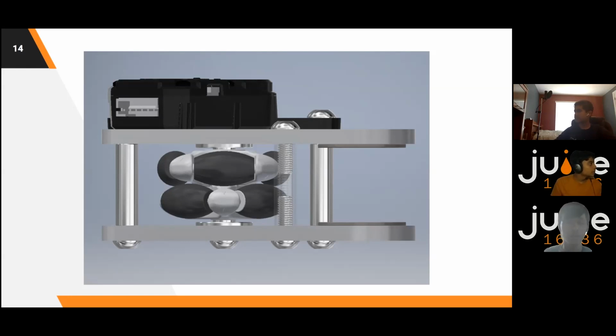How does your robot deal with obstacles with dead wheels? So we were able to use our dead wheel odometry. We had the 2-axis odometry where we had 2 wheels, and we combined that with our PID loop. We actually experimented with literally just kicking our robot in the middle of its auto path, and what we'd see is that we have 3 concurrent PID loops running: one for rotation, one for the horizontal movement, and one for the Y movement.